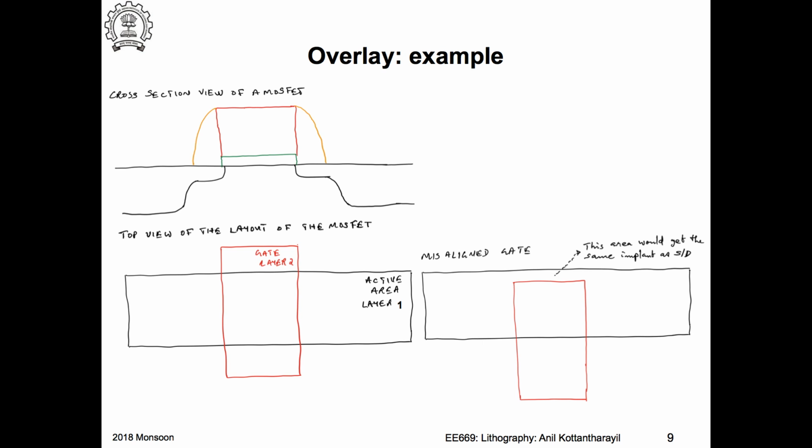So around this would be oxide, and maybe there is another transistor here and so on and so forth, right? In the immediate neighborhood, you have oxide, and then you have a gate. So I define this by using a lithography step. I make my isolation, and then I deposit my polysilicon, implantation and all these things. I grow the gate oxide, I deposit the polysilicon everywhere. I now want to pattern my gate, which will give me something like this.